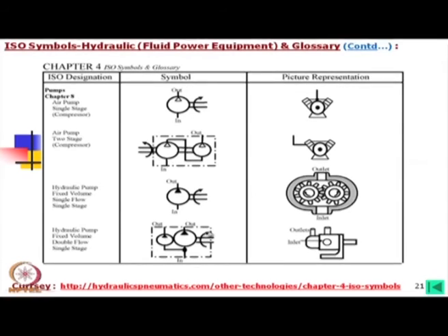When you find that you have to use this one also, you can set the pressure. In many cases you will find that these two pumps are used when there is a low flow requirement, only this pump is working. When high flow is required at low pressure, then both the pumps are working, which we have already learned, how the two pumps can be used. In that case, we go for such a pump. It reduces the total power consumption.